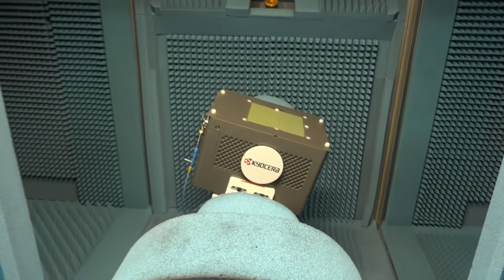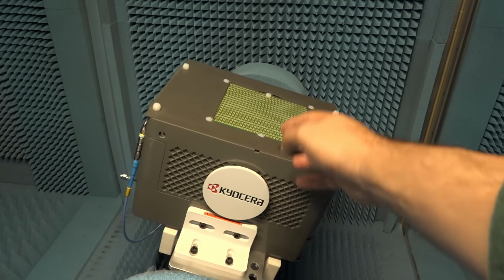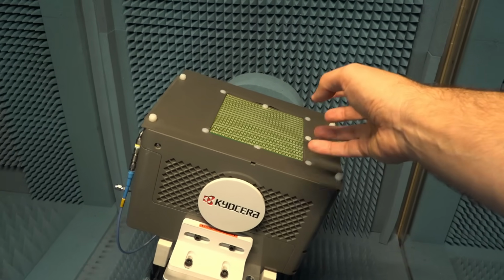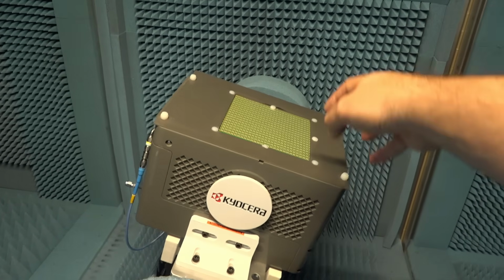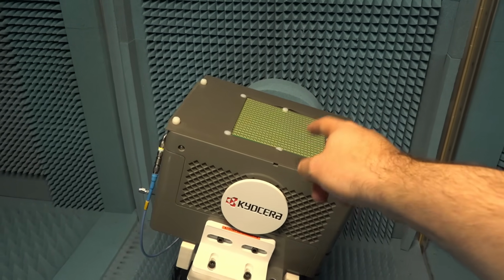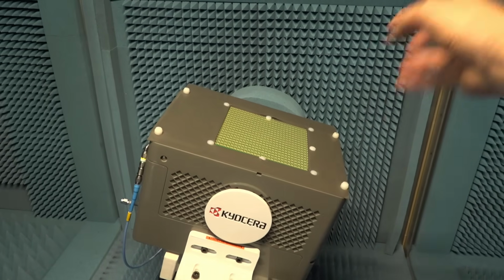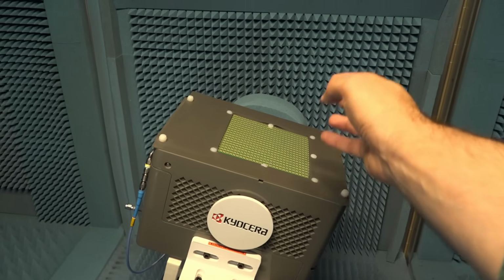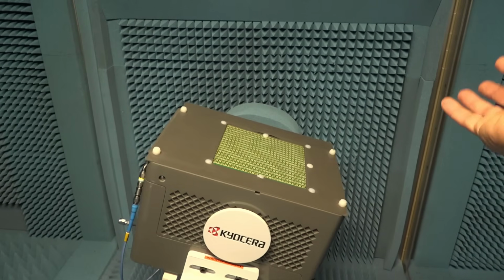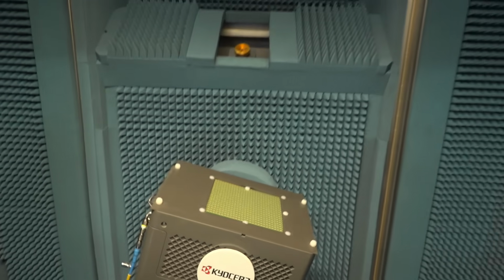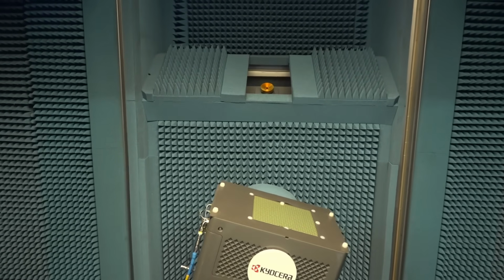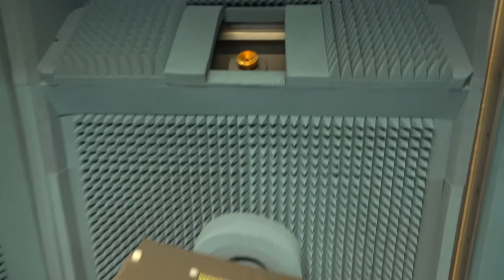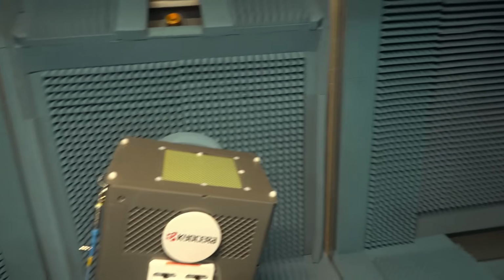So the question becomes, why would you want to do something like this? Well, imagine you have a large-scale phased array, something like this, that's built in quadrants, is able to do multi-beam, and it is receiving and transmitting signals in different directions. What you want to do is find out how this behaves in a dynamic environment with simultaneous beams coming in at the same time. You can have an imposing beam that's causing interference, or you may be just talking to 4 different end units and you want to see how that behaves. All of that can now actually be done inside of this one chamber because you have multiple reflectors, multiple transmit and receive units, so you can both excite and measure this array from multiple angles.